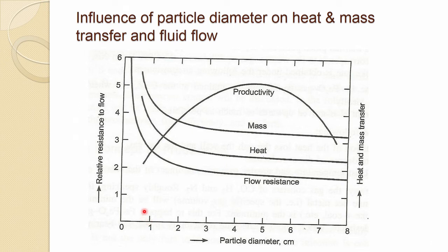However, the flow resistance to fluid flow will increase substantially, because that high surface area will give a big resistance to the gas flow, and this is not desirable at all.